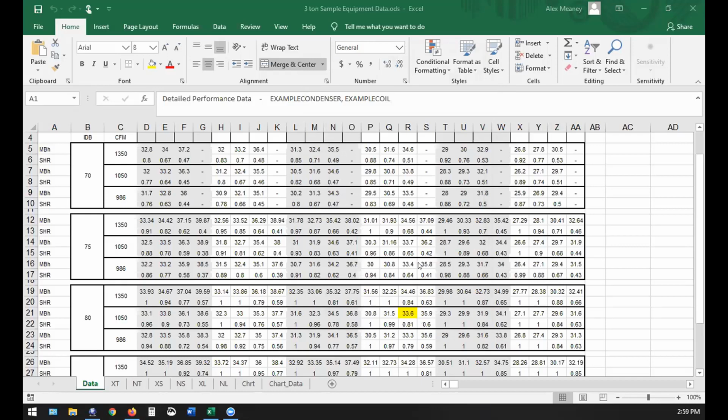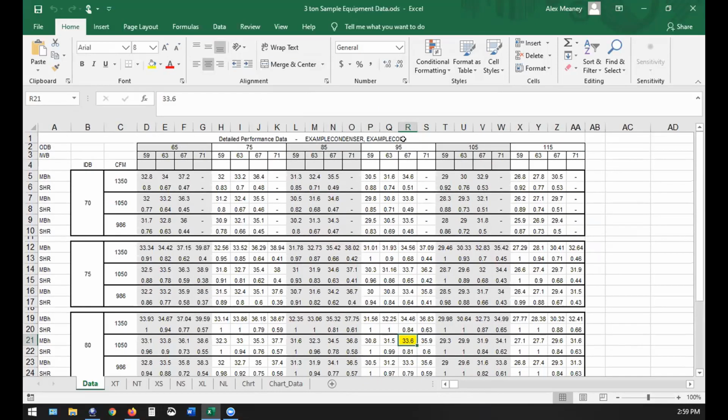And ice melting doesn't change when you change the humidity or the outdoor temperature or any of this other stuff. Equipment capacity does. This little guy right here is what AHRI capacity is, and AHRI capacity is at 95 degrees. So when you look at AHRI and you say this system is 33,600 BTUs, which is what that says, you go to AHRI, it says it's 95 degrees outside with an 80-degree return, 80-degree return, folks, with a 67-degree wet bulb. That's where AHRI gives you that 33,600 BTU rating.